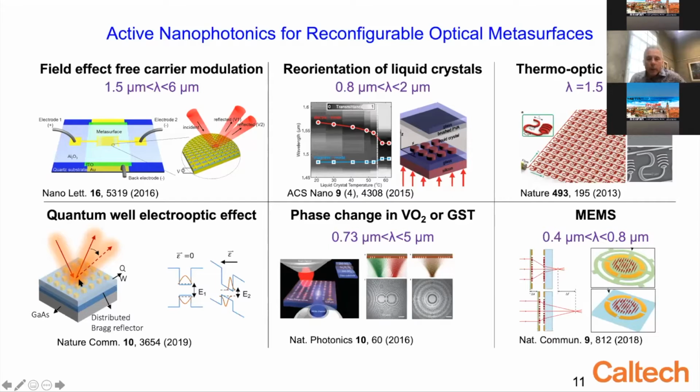And these same structures are effective at optical frequencies in the C-band, telecom band. These are dielectric structures. They're not plasmonic, they're not metallic, they're all dielectric. And they operate by shifting the electronic wave function and changing the permittivity associated with confined electron-hole pairs in the semiconductor quantum well.